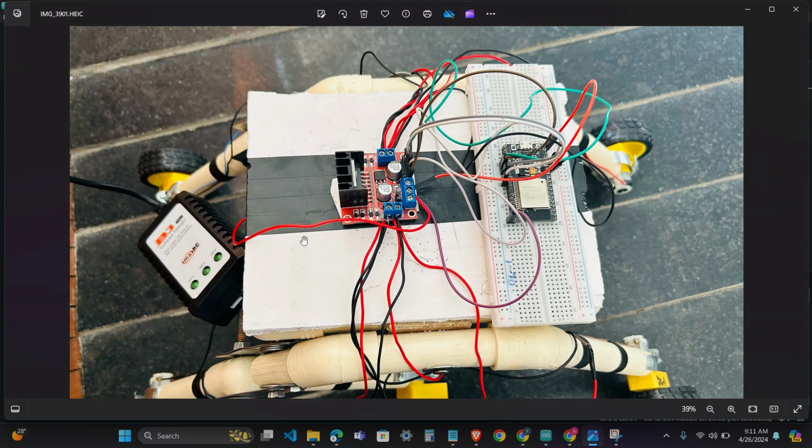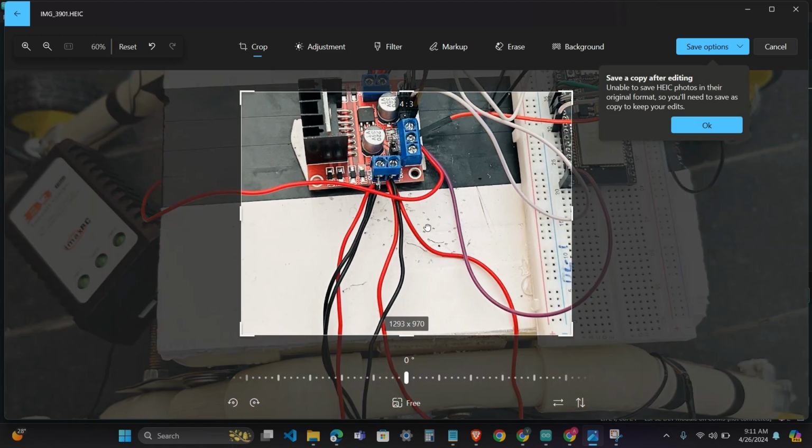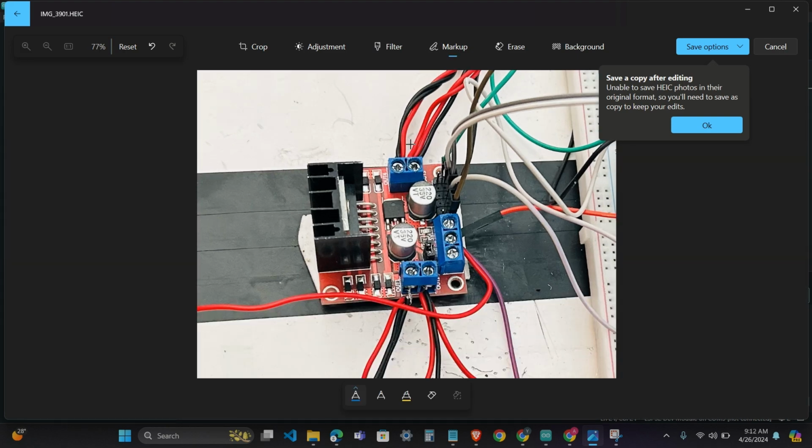The reason we need six button states to control our rover is that we used an L298N motor driver to control the motors of our rover. We used only a single L298N motor driver. This motor driver can control two motors at a time, from these two outputs. It has six inputs, out of which four are digital and two are analog.